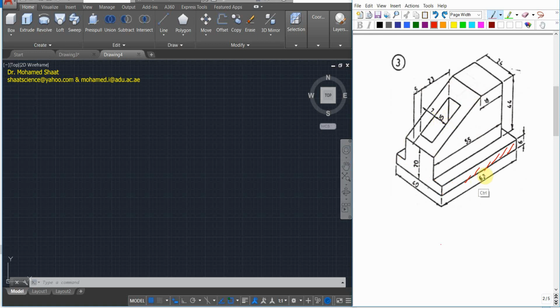But simply, one of the shortest or the simplest approaches, we can start by creating the base. Like we can draw this face, definitely this is gonna be the front view, right? And this is gonna be the left hand side, and this is gonna be the top view. So over this front view, I'm just gonna draw the shape, which is just a rectangular shape with 62 length, height of 6.